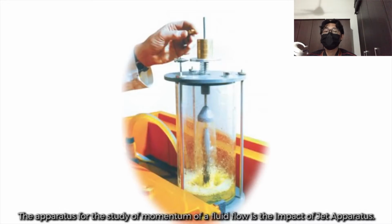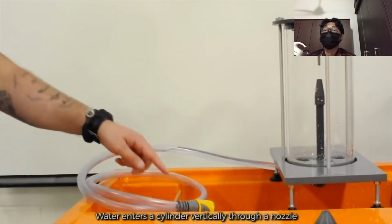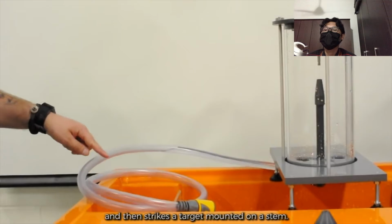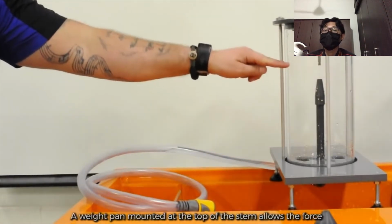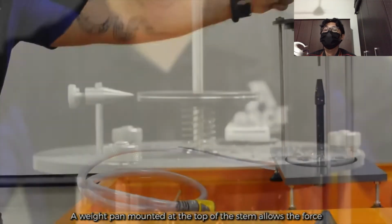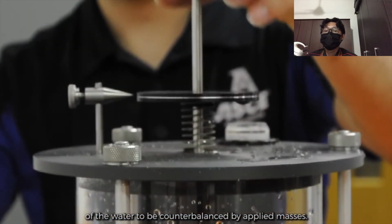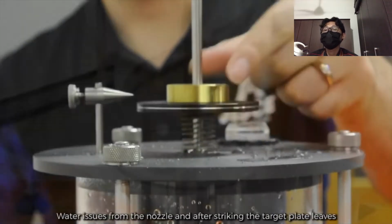The apparatus for the study of momentum of a fluid flow is the impact of jet apparatus. Water enters a cylinder vertically through a nozzle and then strikes a target mounted on a stem. A weight pan mounted at the top of the stem allows the force of the water to be counterbalanced by applied masses.